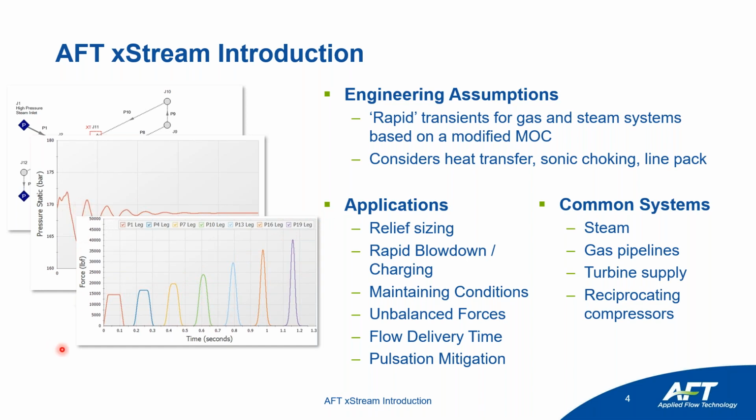We have a great technical paper that covers this in a lot more detail than we will here. But if you're in pipe stress analysis or you're sizing supports for piping, and you're basing it off of transient forces, it's important to consider that compressible flow doesn't behave the same way as a liquid. You can see these more dramatic forces over time.